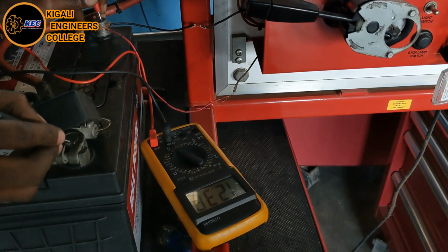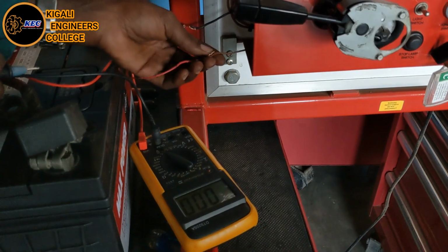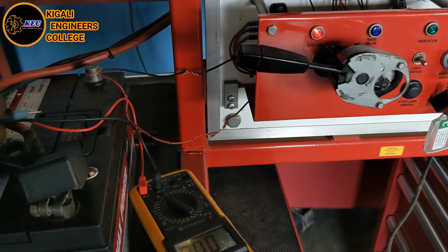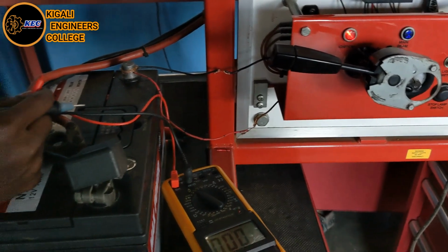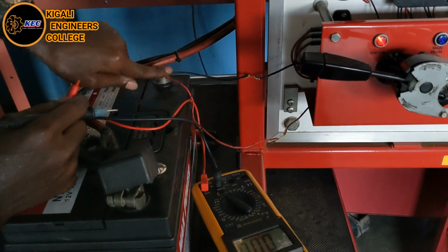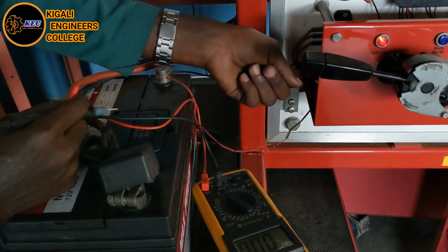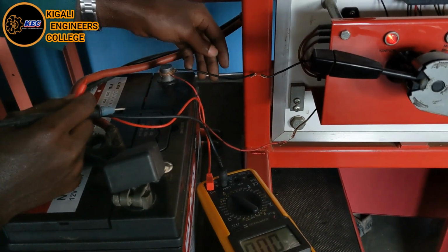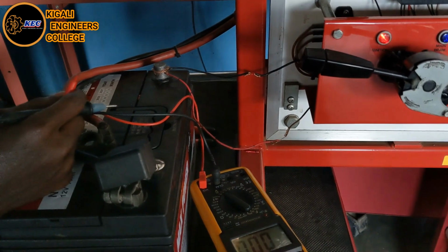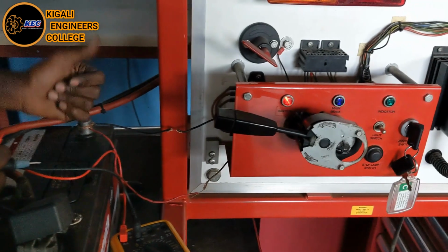So we see this wire, it is the ignition wire, as you see on the drawing we drew on the board. It is a wire from the battery positive through the ignition, but we bypass it. And this one is the wire carrying the charging voltage from the power diode to the battery in order to charge it.